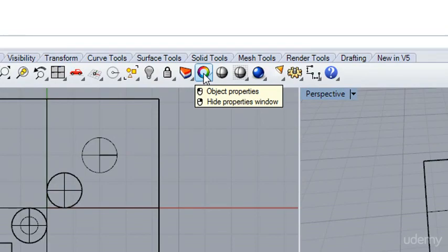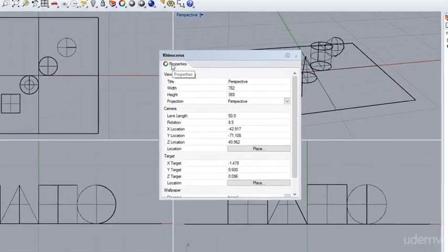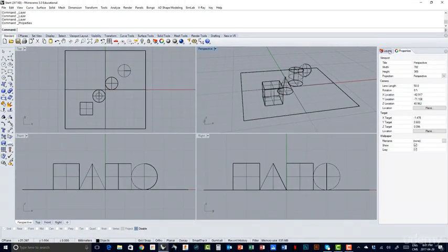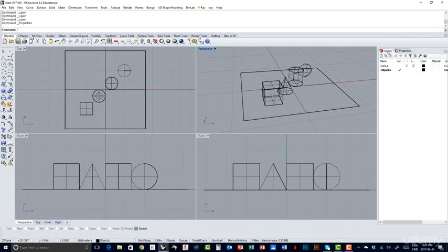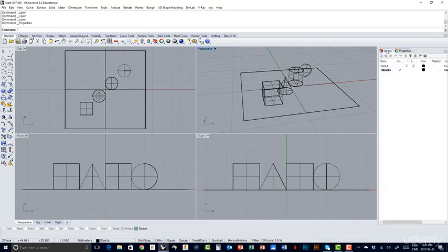I'm also going to left click right next to the layers tab. It's called the object properties. So I just left click and I'm going to take the tab from the properties, and I'm just going to drag it as such and bring it into the window like that. Okay, so now I've got the layers and properties tab open in a permanent way, and you won't have to deal with this in the future.